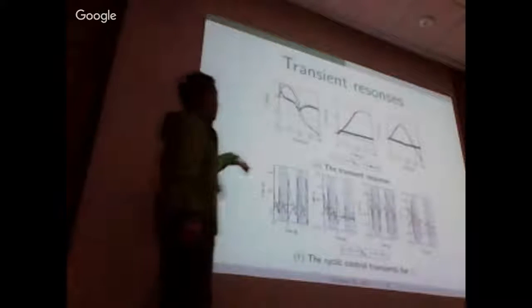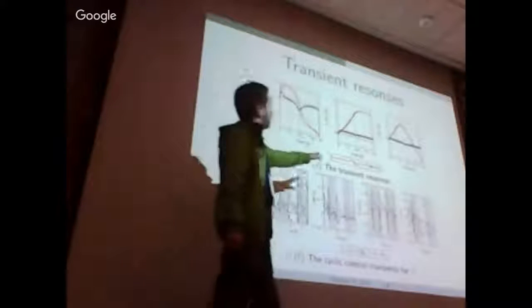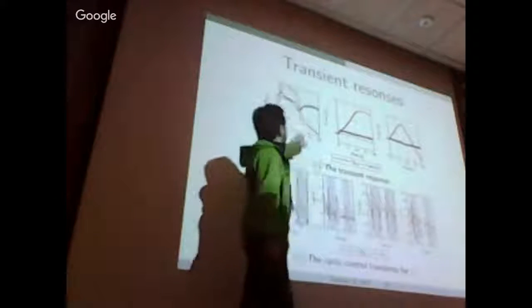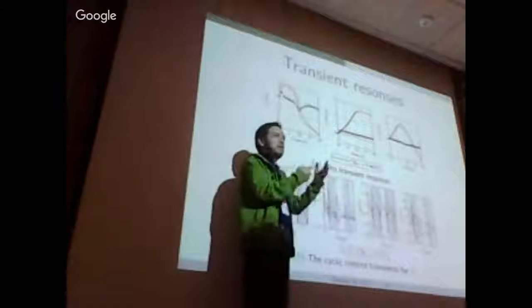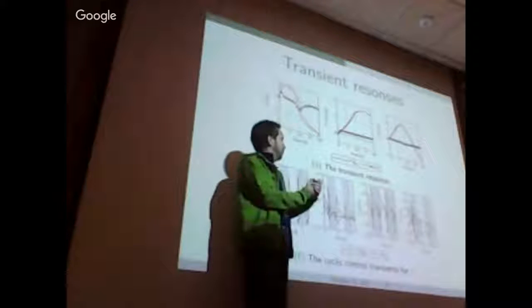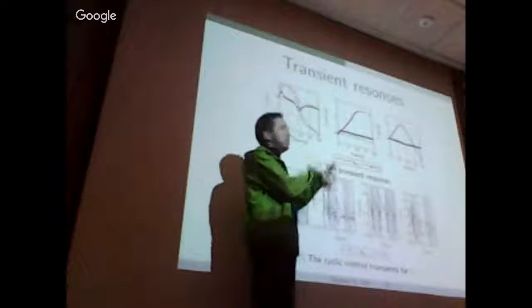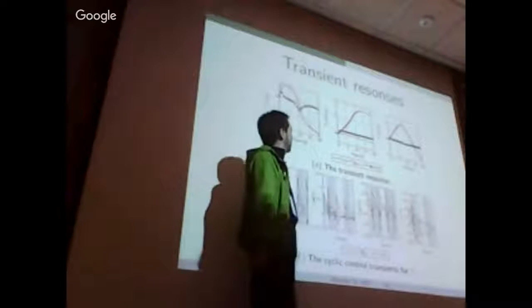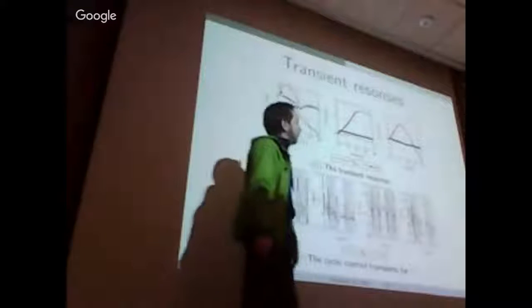This is just the transient response. At the beginning, the robot aligns with the XY axis. You can see how the two legs are getting too close to each other. There has to be some error to track this trajectory. So they are always almost overlapping, but not touching each other. The error stays close to zero.